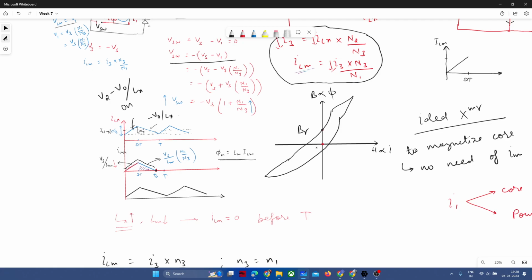And if we do not bring it back to 0 every time, well before the end of the time period of that cycle, then what will happen? This flux will be added cumulatively and it will lead the core to saturation, and after that it will demand an enormous value of current. That was my explanation for that reason. So from this BH curve, we have to make negative ampere turns available to make it zero. Yes. Suppose for CRGO, Br is around 0.6 Tesla, and it will demand a certain amount of ampere turns to bring it to zero in the negative direction. You are right.